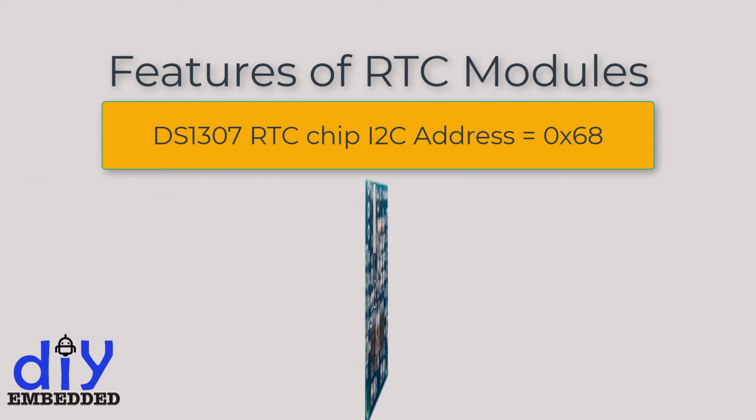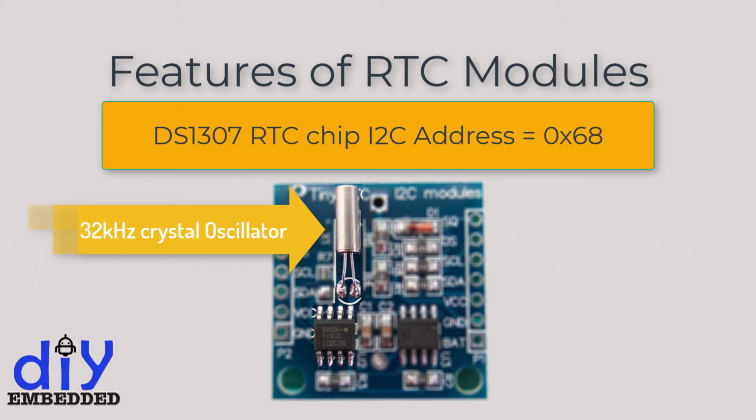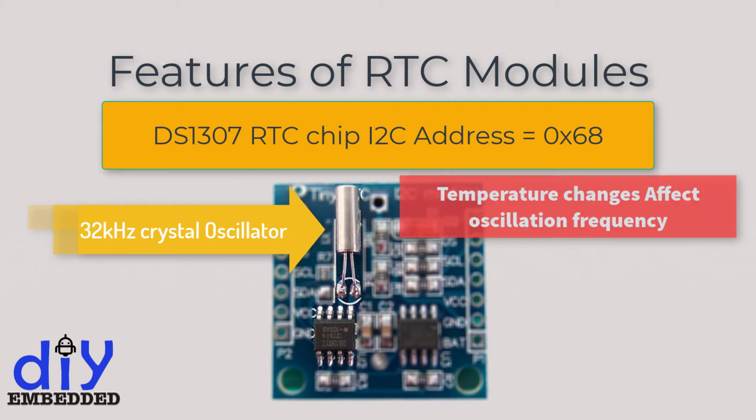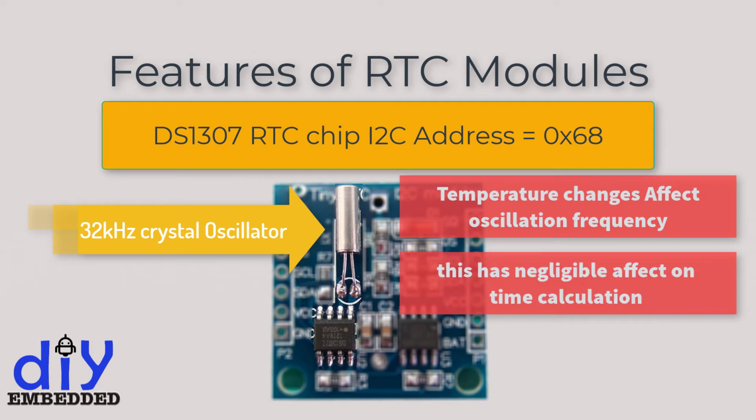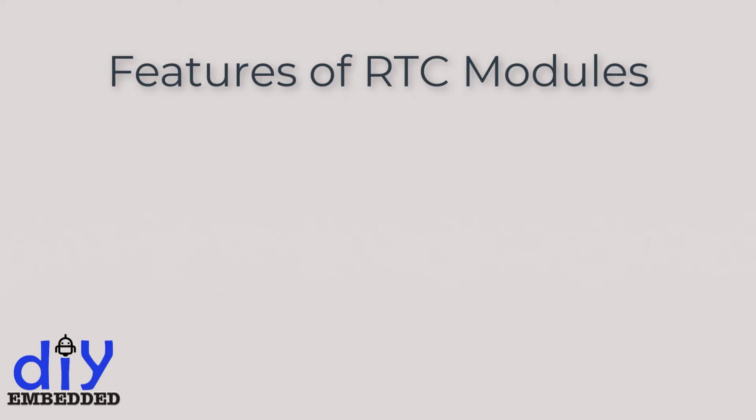Note DS1307 comes with an external 32 kHz crystal for time calculation. The problem with these external crystals is that temperature can affect their oscillation frequency. This change in frequency is negligible, but it surely adds up. It actually results in the clock being off by around 5 or so minutes per month.